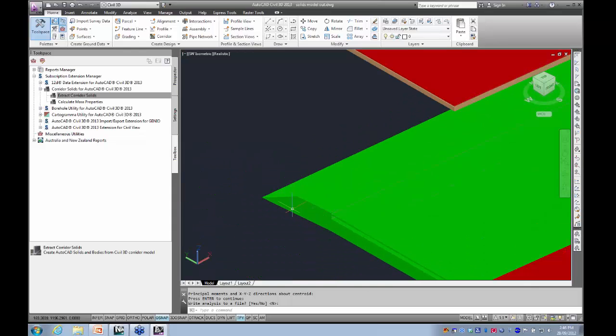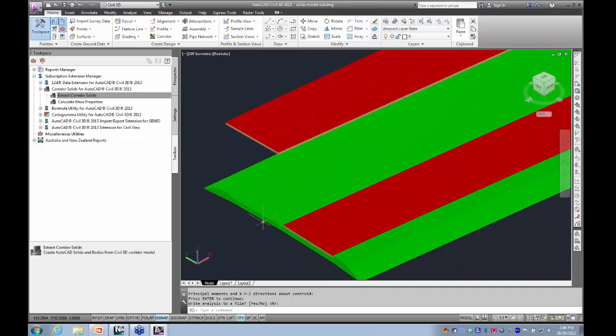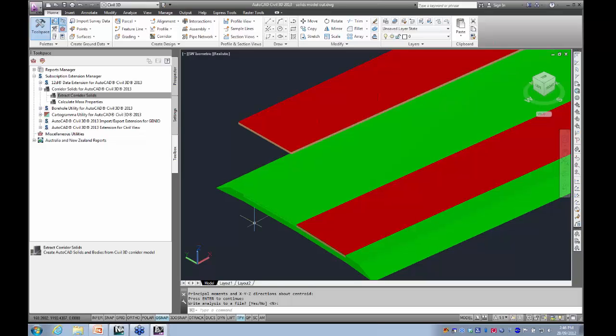But what this is really for is to now be able to take those through to Navisworks. So for those who aren't familiar with Navisworks, it's been used by architects and structural people for a long time, in that you can take different models from, for instance, all your ducting, your structural steel work, your architectural walls, bring them all together in Navisworks, make one model out of them and see where they clash and do timelining and how you're going to construct it and how things are going to work around each other as they get constructed.